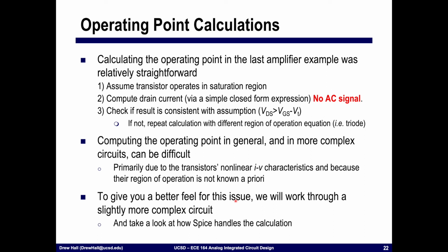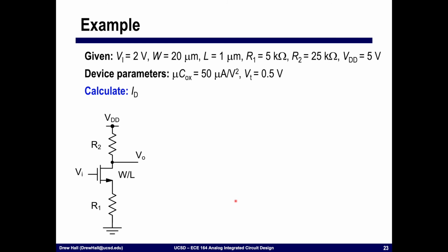All right, so somewhat familiar circuit. I've added another resistance in the source. Okay, so I've added drain resistance. I have a MOSFET, an NMOS, size W over L, and I've added a source impedance down here, R1. We're still taking the output at the drain and applying the input at the gate.